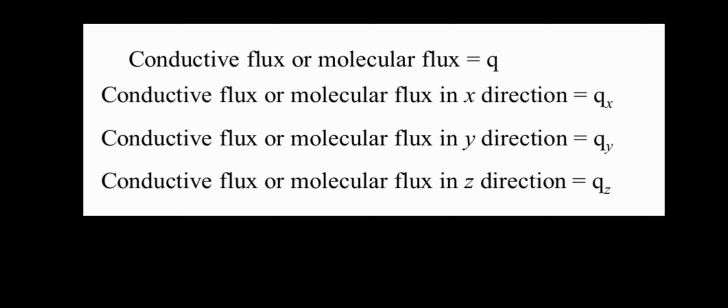Where T is the temperature, the proportionality constant is the thermal conductivity of the fluid. Therefore, the conductive heat flux vector Q represents the rate at which thermal energy is being transported through the fluid due to these molecular interactions driven by temperature differences. Even if the bulk fluid is not moving, heat can still be transferred from a hot part to a cold part through conduction. Imagine you are placing a metal spoon in a hot cup of coffee. Even if the coffee itself isn't swirling, the heat from the coffee will travel up the spoon through conduction due to the vibrations and collisions of the metal atoms. Similarly, within the fluid with a temperature gradient, heat will be conducted from higher temperature regions to lower temperature regions.